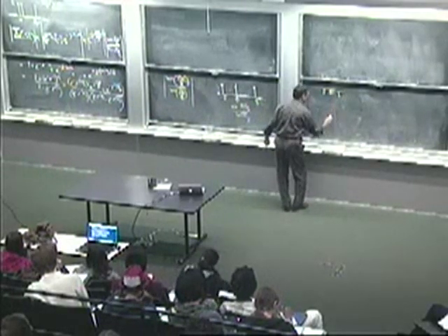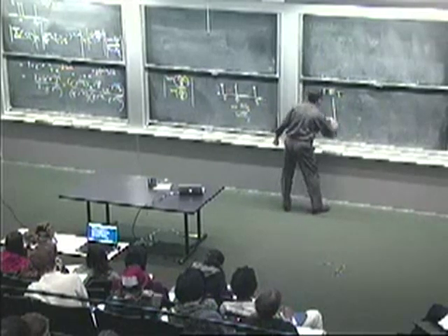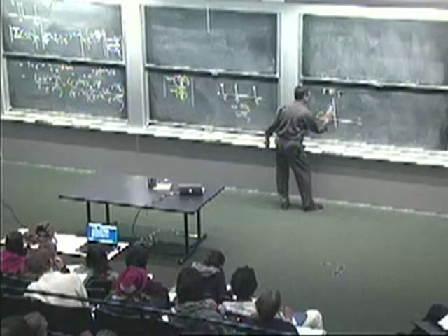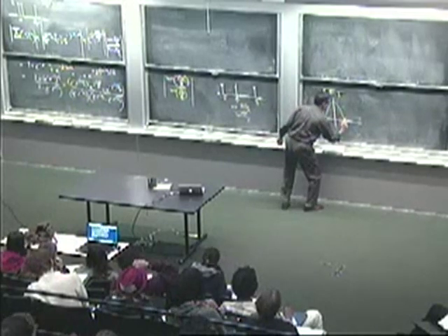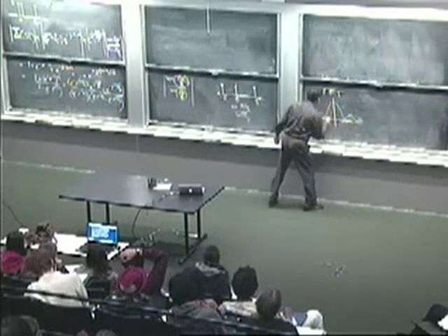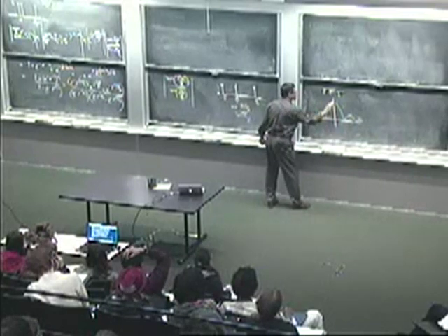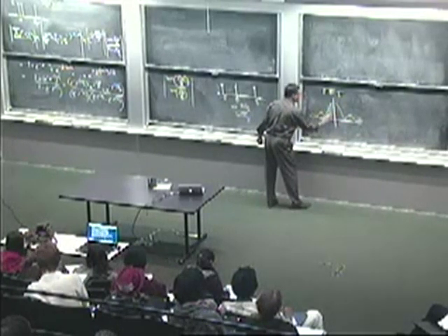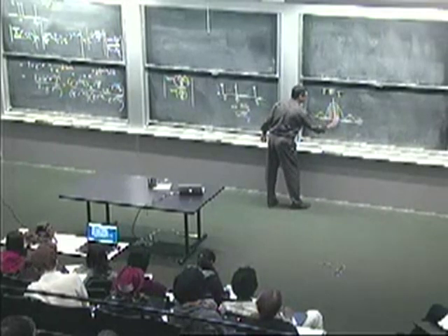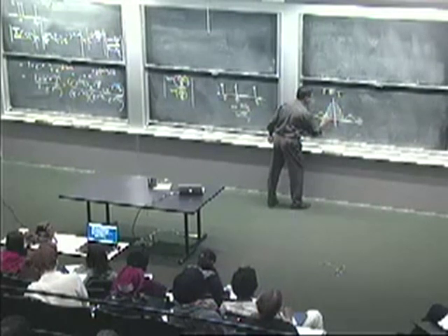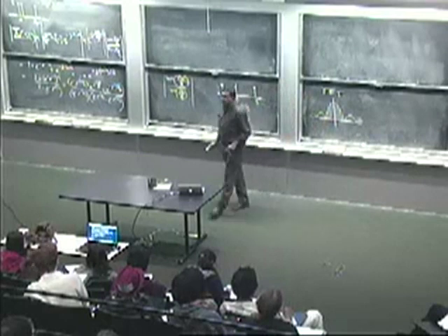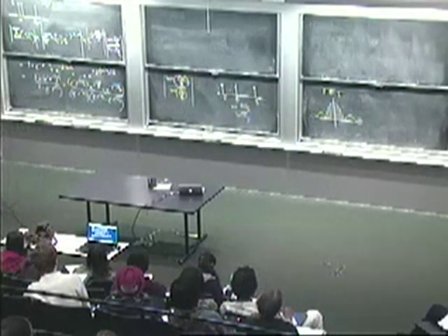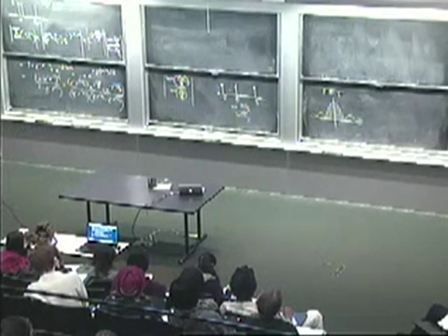So what the fast Fourier transform is going to do is, if the actual magnitude of the DTFT was some continuous thing like this, the fast Fourier transform is going to give me samples of it, as many as I want. But the more samples I ask for, the more work I have to do, of course. Okay, I asked for 48,000 samples of the DTFT so that I could get a nice big spread here.